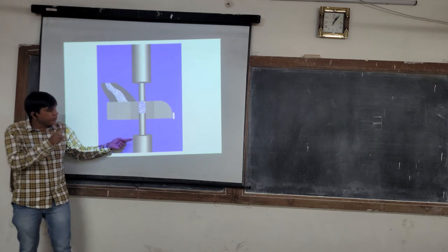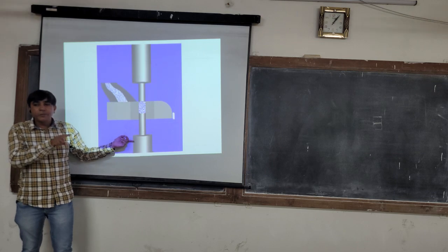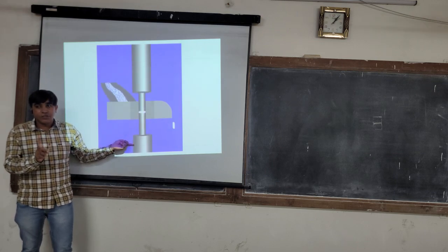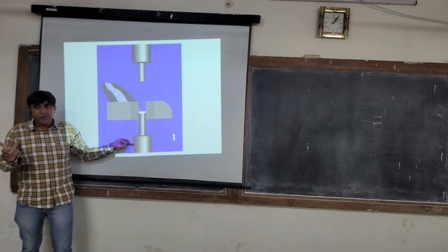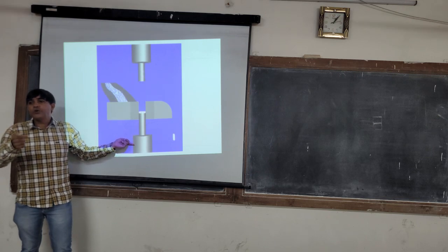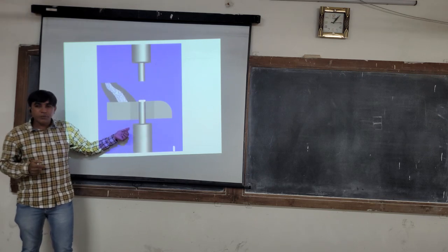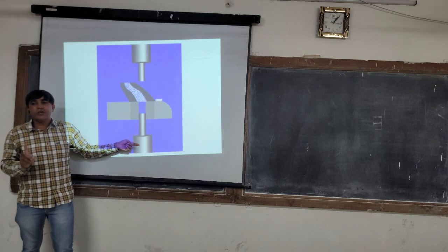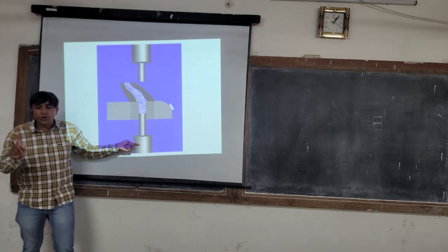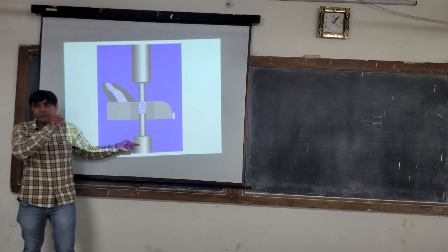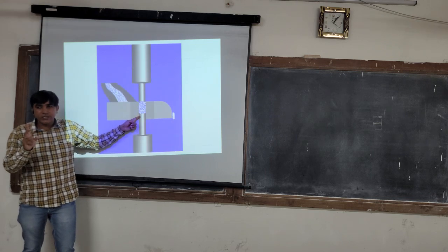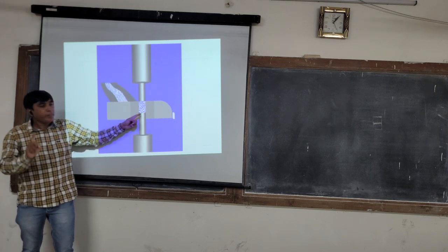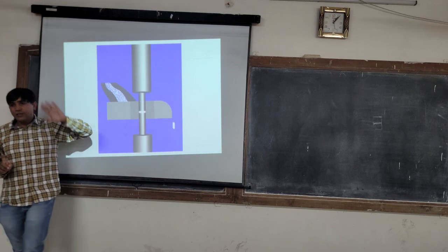Look at the compression cycle closely. During compression, the lower punch is stationary. It is not moving. In a rotary tablet machine, the lower punch will also move during compression. In a single punch tablet machine, the lower punch will not move during compression. So compression force is only adjusted by the upper punch. The lower punch has two tasks: volume adjustment and ejection. The upper punch only facilitates the compression.